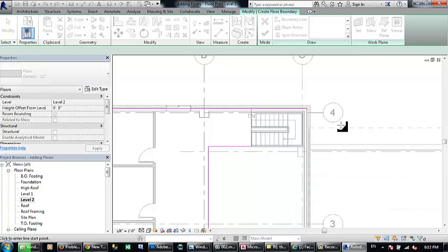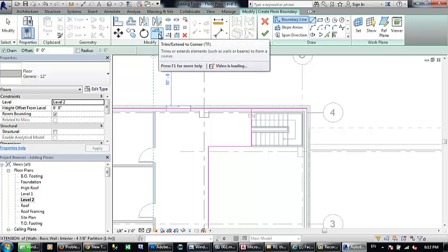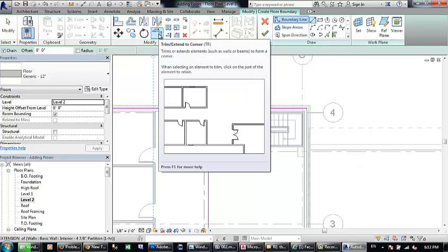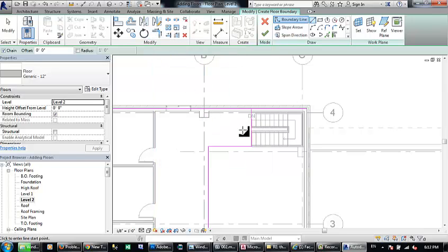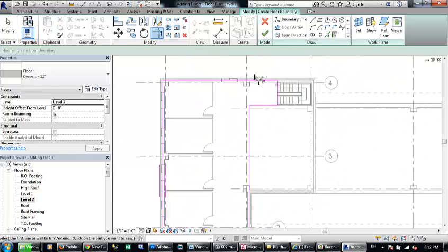So I'll click on continue, and then I'll use the fillet tool. This is a trim or extend. You know, when you go to the fillet command in AutoCAD and press the radius, set the radius to 0, you make a corner. So as the help here mentions, it is either extending or trimming. In our case, I want to trim, so I will click this wall and click this wall, this line and this line, and they will be trimmed and the excess lines will be removed.